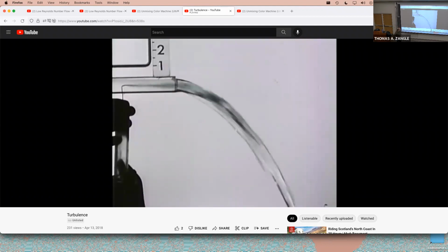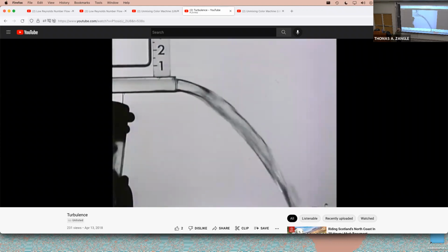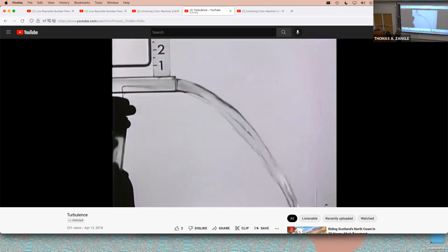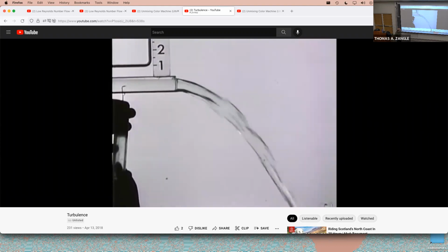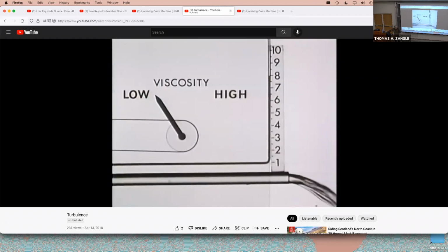The fastest fluid is not quite so fast, and there is very little slowly moving fluid. What little there is can be dragged along with the rest as it leaves the pipe. Nevertheless, the velocity must vanish at the wall, so we can regard the wall as a sink for momentum. Turbulence increases the rate at which momentum is transferred toward the wall. Thus, with turbulence, we need a larger pressure gradient to replace the momentum lost to the wall.